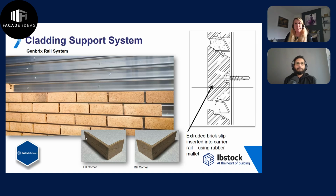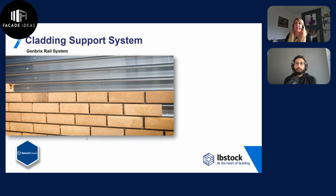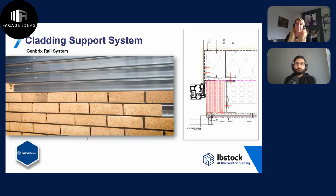You can see there we've got corner profiles, but these are generally used for the building envelope itself, and typically where we have window jambs or soffits, we would only use that flashing detail. So again, check out all the detailing of the system that you're proposing to look at.